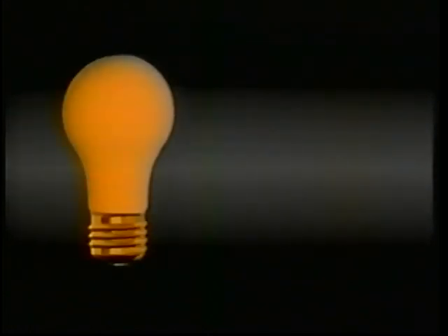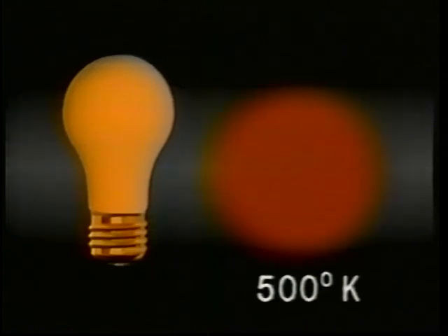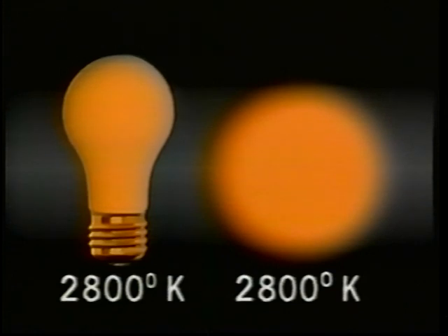The color temperature of every incandescent source of light is assigned by comparing its radiation to that of the theoretical blackbody. The temperature of the blackbody, where its light most closely matches the light source, is then used to designate the color temperature of the source. The actual temperature of the filament, however, is not necessarily the same as the color temperature of the lamp. A key point, though, especially with respect to fluorescent light, is that a blackbody is a continuous spectrum radiator, while fluorescent light does not radiate a continuous spectrum.